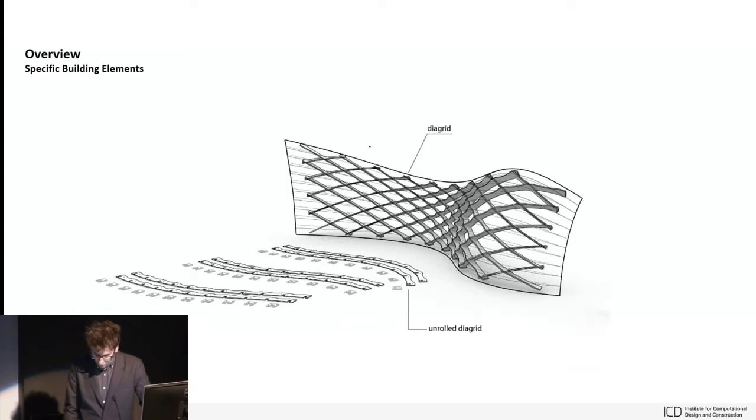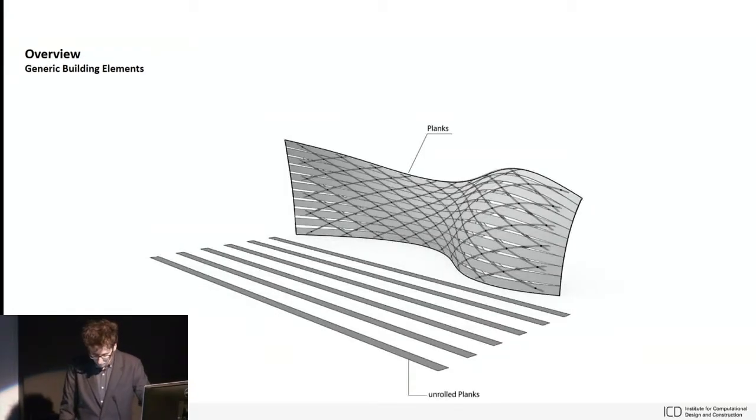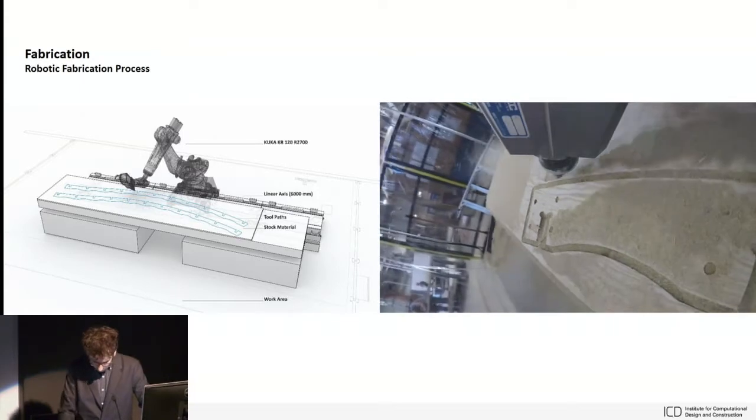And then once that is assembled, by having some indication points on this substructure, you know exactly where to put the planks. And these facade planks are completely straight. They are standard cedar cladding planks, and you simply put them on point by point, and by that you also make this whole structure very rigid. So both the planks and the diagrid substructure have structural purposes, and together they form this very rigid system.